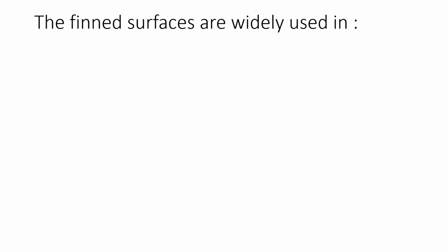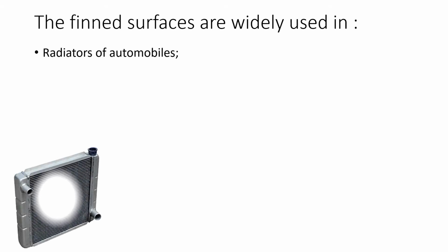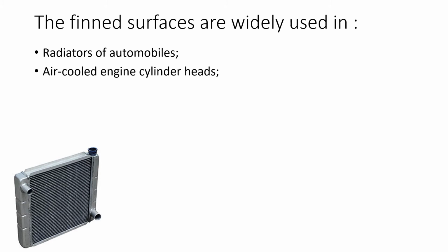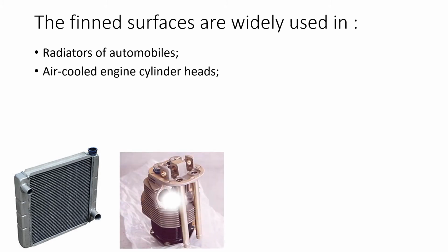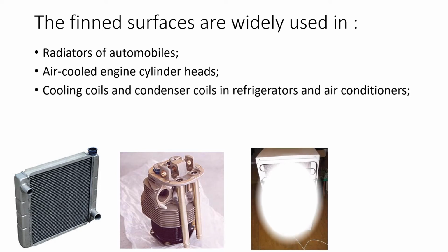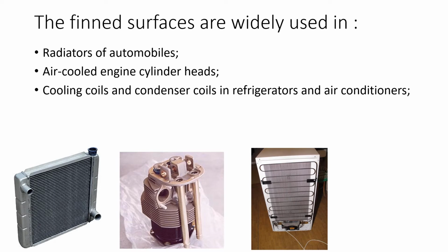There are many applications of fins. First application is radiators of automobiles. These are fins to release the heat. Second application is in air-cooled engine cylinder heads. You can observe the cylinder heads have fins so that heat produced inside the cylinder in the power stroke can be released. Third application is cooling coils and condenser coils in refrigerators and air conditioners.